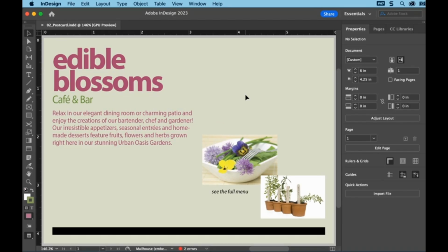typical work for entry-level InDesign users. Currently, the postcard document is displayed in preview mode, which displays artwork in a standard window, hiding non-printing elements such as guides, grids, frame edges, and hidden characters. To work on this document, you will view guides and hidden characters, such as spaces and tabs. Click and hold down the Screen Mode button at the bottom of the Tools panel and choose Normal from the menu.